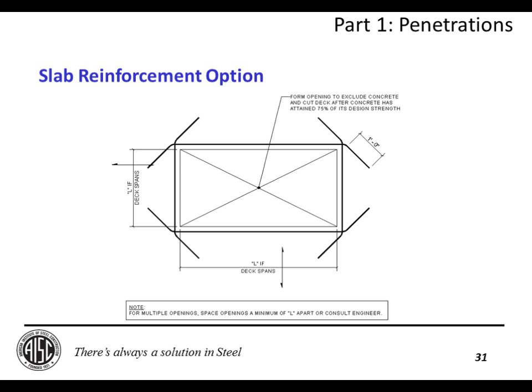The next question we have is on camber. What would you suggest as criteria if the specified beam camber on the documents does not come out upon concrete pour? What thickness of concrete limits would you stop at for deeper or shallower conditions? So I think what he's talking about there is where you don't have the specified cover if the camber doesn't come out.